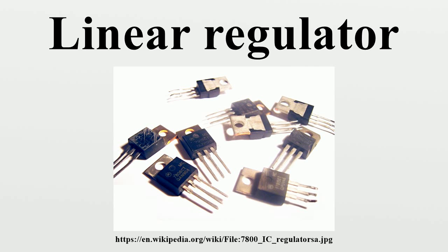When the supply voltage is less than about 2V above the desired output voltage, as is the case in low-voltage microprocessor power supplies, so-called low dropout regulators must be used. When the output regulated voltage must be higher than the available input voltage, no linear regulator will work. In this situation, a switching regulator of the boost type must be used. Most linear regulators will continue to provide some output voltage approximately the dropout voltage below the input voltage for inputs below the nominal output voltage until the input voltage drops significantly.